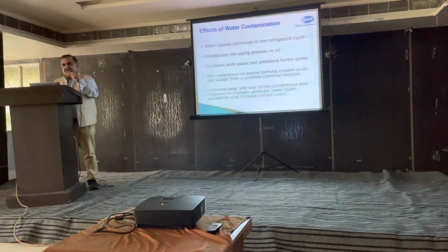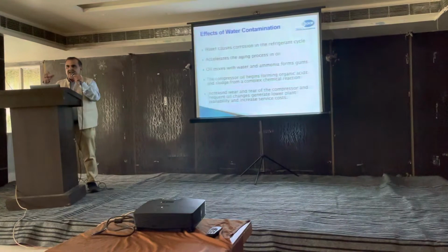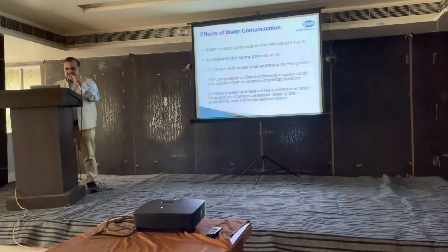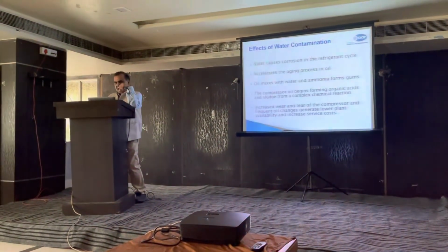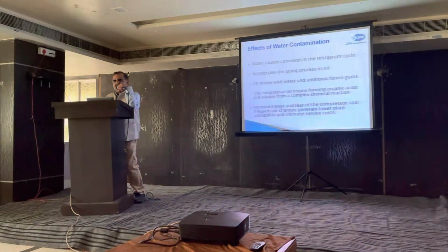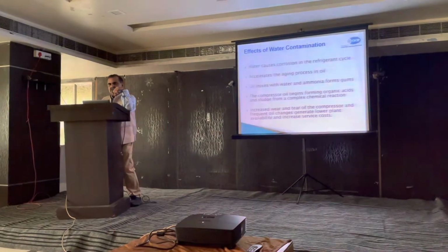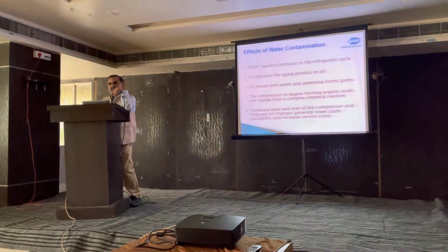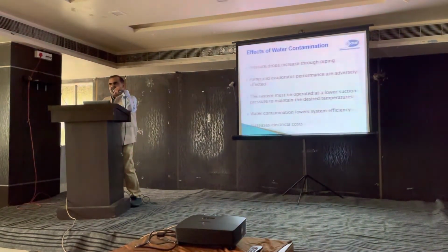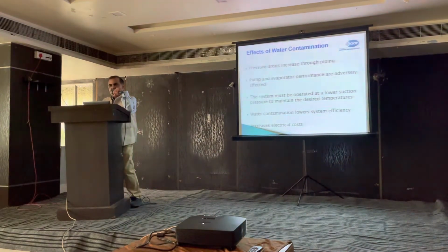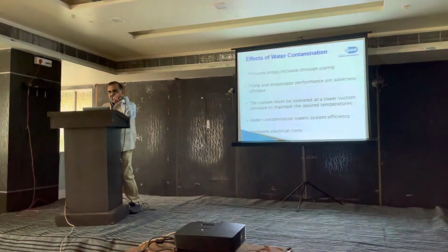Now when oil is mixed with water and ammonia, it will form a solid gum, something sticky. It will get stuck in the compressor or many other parts. Then this sludge will accumulate in your filters, choke filters, and compressors. Of course, compressor wear and tear will increase, oil consumption will go up, and overall maintenance service cost goes up. As there is sludge formation on the pipeline walls, there will be more pressure drop in those areas because of the restrictions, and overall efficiency will be affected.